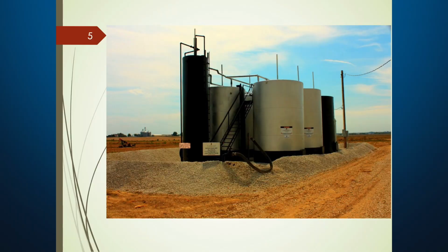Seth kind of touched on the enhanced oil recovery, and he mentioned secondary water flooding. The enhanced beyond secondary is tertiary, which may involve polymer floods, may involve surfactants, just all kinds of different things to actually separate those remaining droplets of oil, which we call residual oil, that's typically unmovable, unproducible, and get those to be produced so we can enhance our oil.